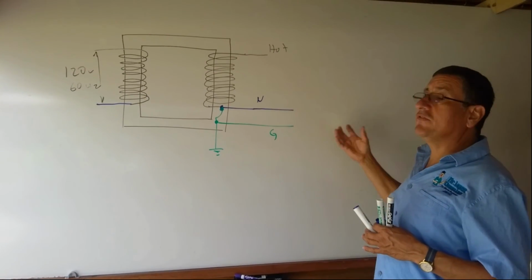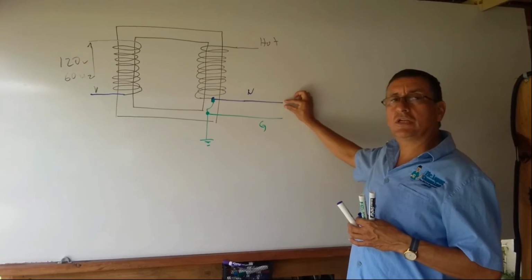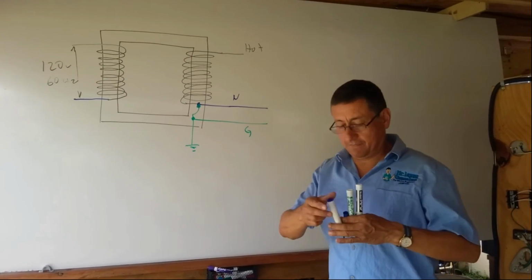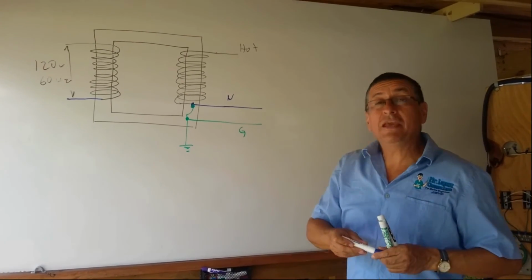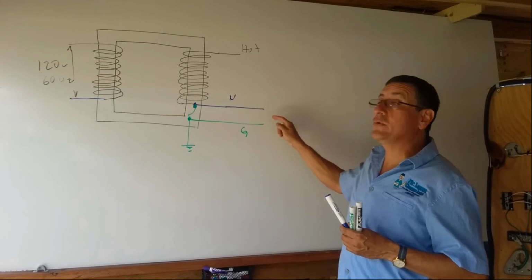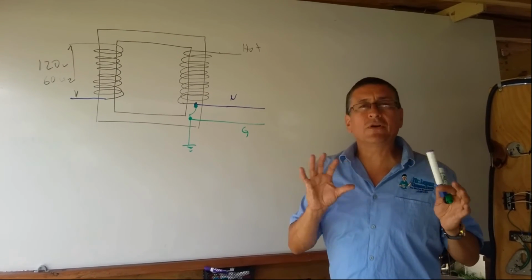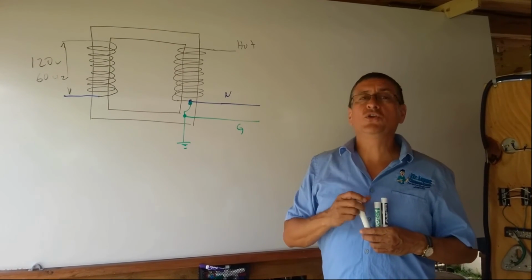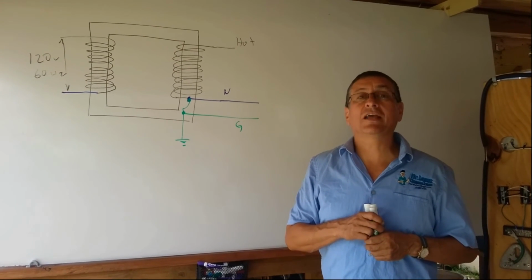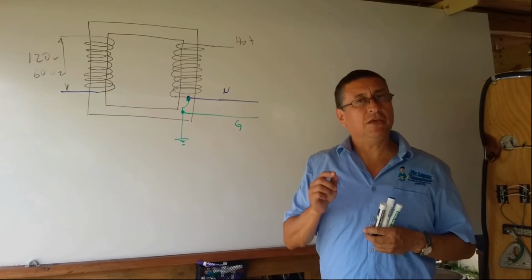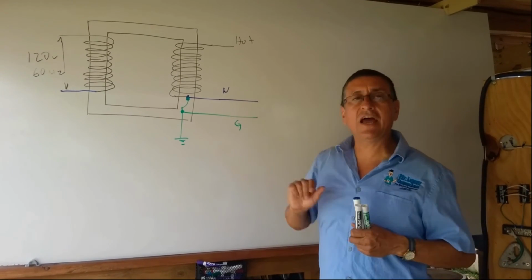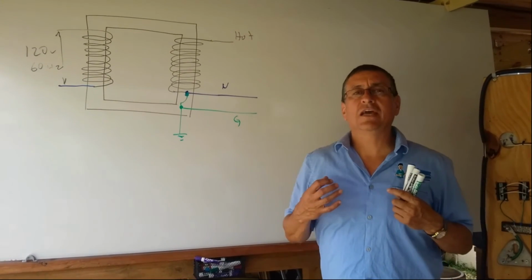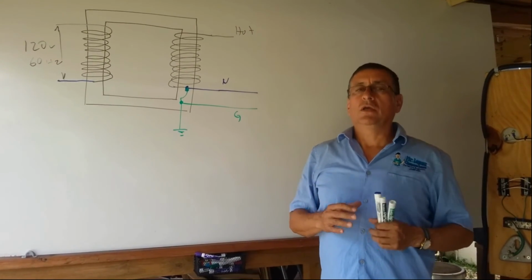Remember, inside of the boat, the bus bar of the neutral and the bus bar of the ground should be separated all the time. Why? Because if you mix them, and for some reason you have reverse polarity, your neutral bus bar is hot, and because the hot is together with the ground, the corrosion in the boats increases, and you can destroy the boat.